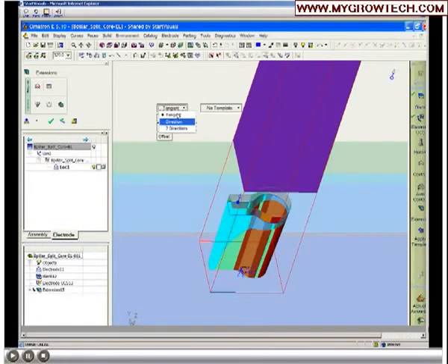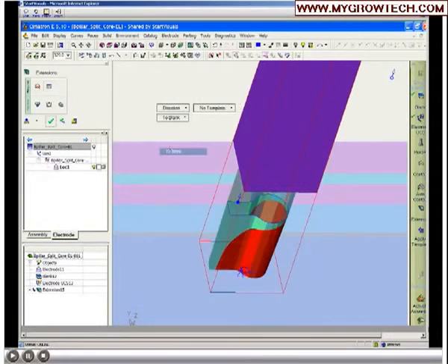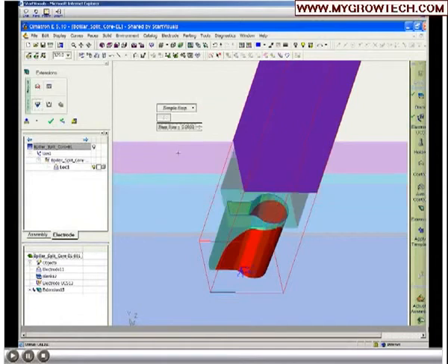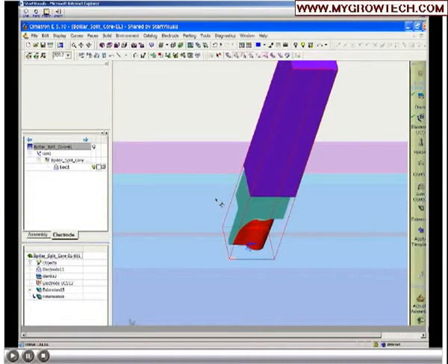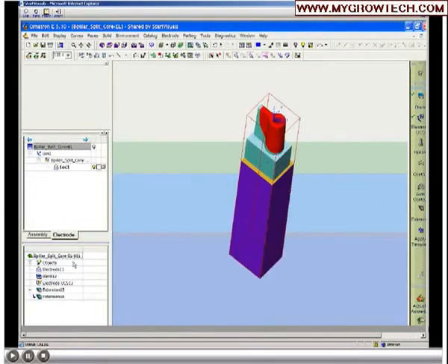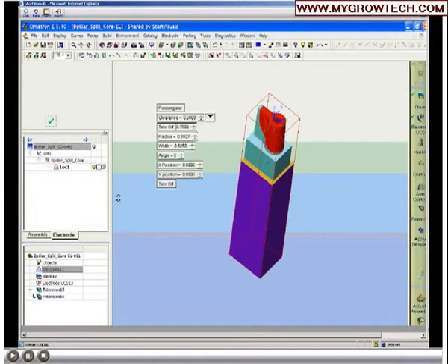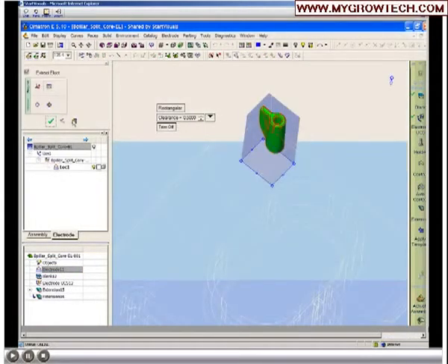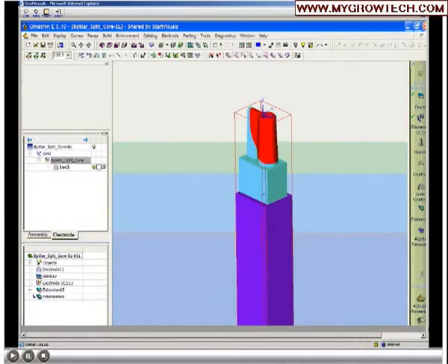Automatically we start building the next one. Drive it straight, maybe take it all the way to the blank. While we're doing that, we can add a step to it, a bit to 50 thousandths, and when we execute it, you can see the completed electrode now. So just that quickly and easily, we pulled out some options that are nice to look at too that I haven't showed you yet. On the blank itself, so there's the completed electrode.